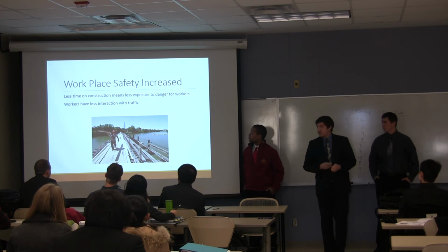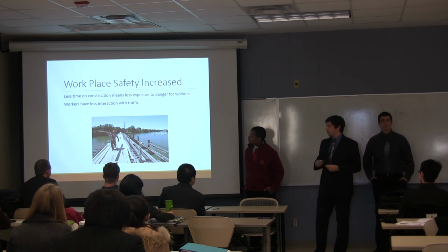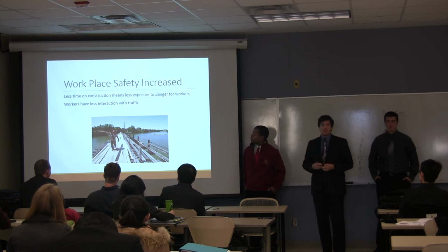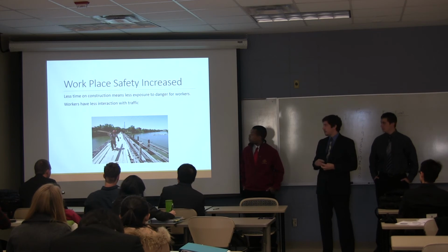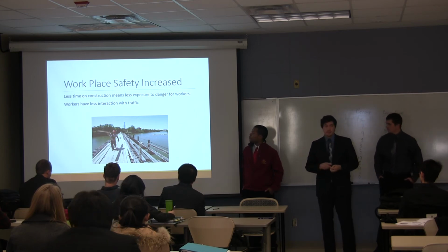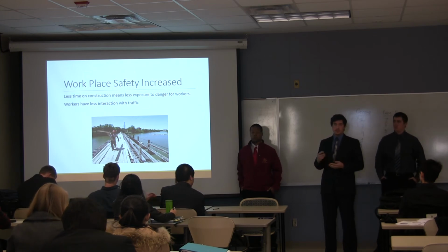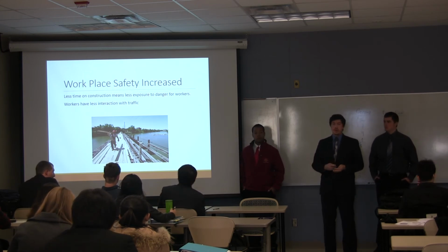Workplace safety is increased. There's less time spent building the bridge. If you're over high waters or a valley, workers have increased risk of workplace mishaps, falling off the bridge and so forth. So you have less time with that. Workers also have less interaction with traffic. If you close the bridge down at night, with less traffic, get it demolished, and then slide the new piece in, have it done.